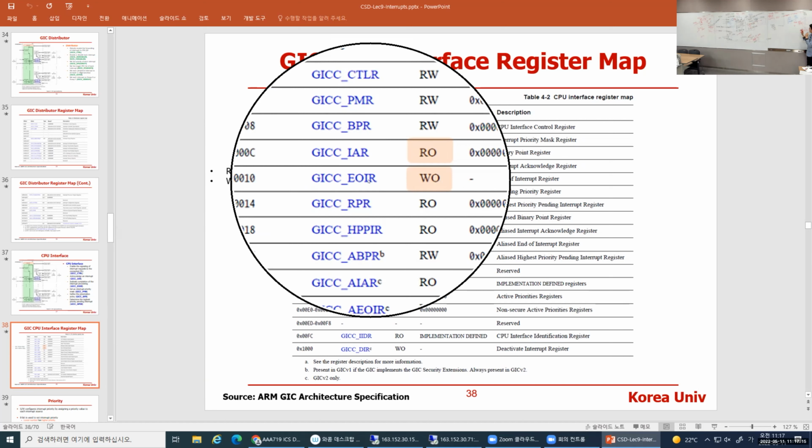One thing you have to be careful about is, besides the protocol with the interrupt controller, GIC, each IO device. If you remember the private timer, it has a decrementing countdown and a status register. That is a sticky bit. That sticky bit will be set to 1 when the countdown reaches 0. Then you have to clear that bit to 0 by software. How to clear? Writing 1 clears it to 0.